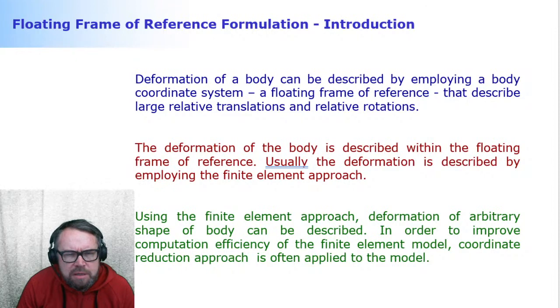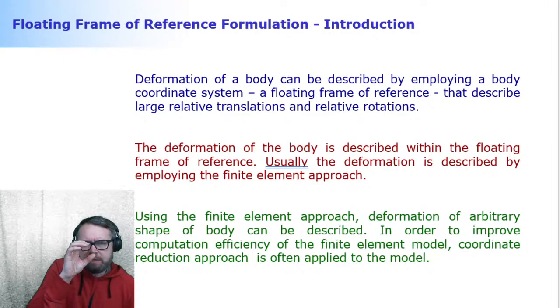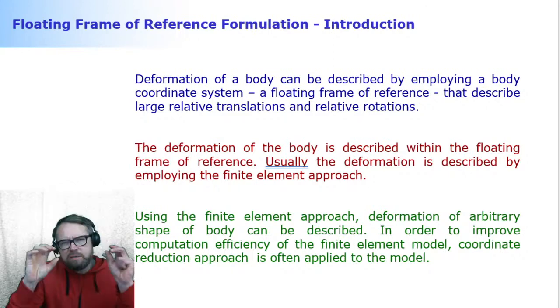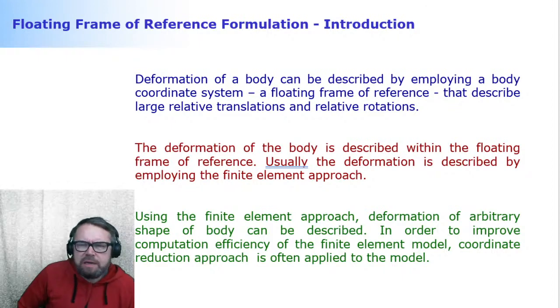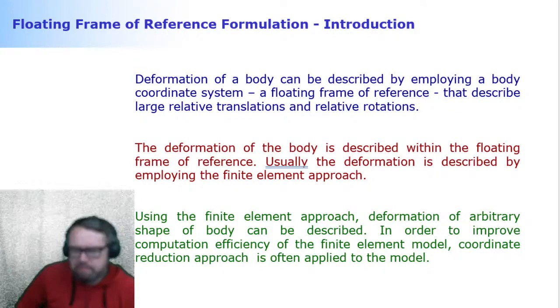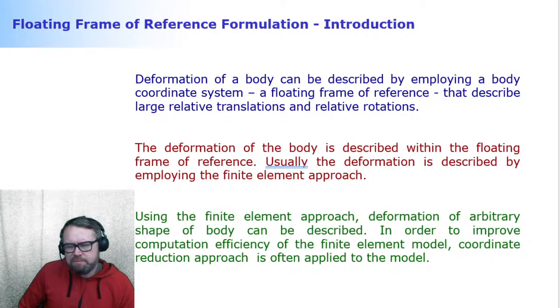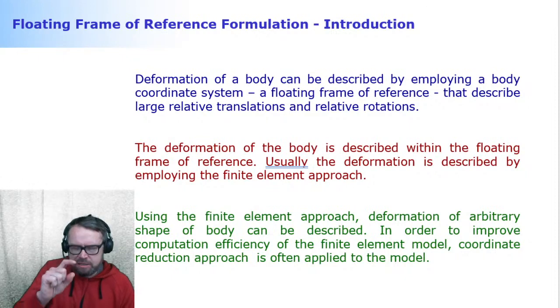So friction is something that can lead to a situation where there's a kind of high frequency vibration. And shortly stated, you're always having difficulties when you have this high frequency and low frequency vibration. Friction, depending on how you describe it, can be a source of this kind of problem, particularly if you use something like LuGre friction, where there's this stick-slip friction behavior as part of the model. So that's a good comment.